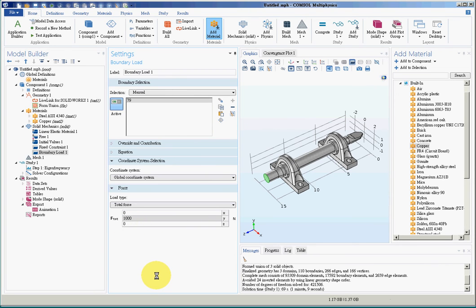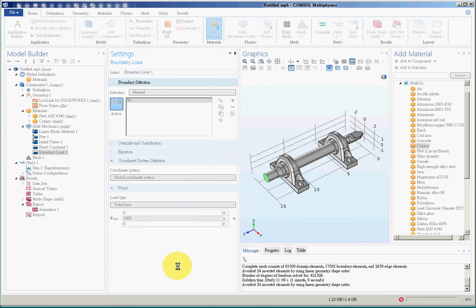Since external load is ignored or blanked out, for example in ANSYS it is blanked out, in SolidWorks simulation the external force item is ignored. But we can see how COMSOL handles external force. We can calculate again, and we will see how COMSOL handles the external force in the eigenfrequency problem.